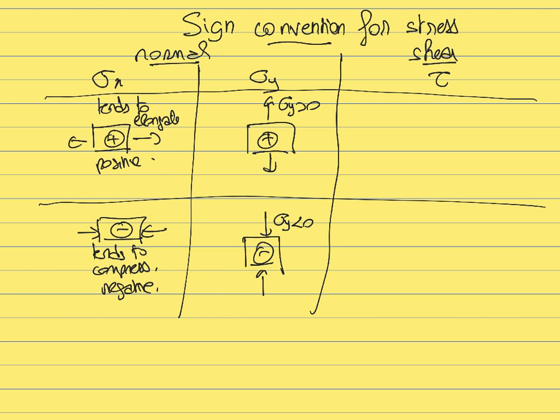In the case of shear stress, a positive or negative shear stress doesn't have any different meaning. It's just about whether the body is going to be deformed clockwise or anti-clockwise. There is really no reason that one should be positive or negative, because it has exactly the same meaning to shear something clockwise or anti-clockwise, which is not the same for the normal stress. It's physically different to elongate and to compress a material.